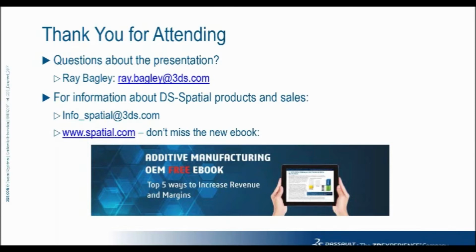That's a great question to help me explain the relative value of having precise CAD data versus tessellated data. Most everything designed in the manufacturing world is designed in a precise CAD system, with near infinite precision and the capability to make smooth surfaces. But if that data has been tessellated and saved as an STL file, it's an approximation. All those triangles you see are an approximation of the true cylinder, sphere or curved spline surface that was the native definition.